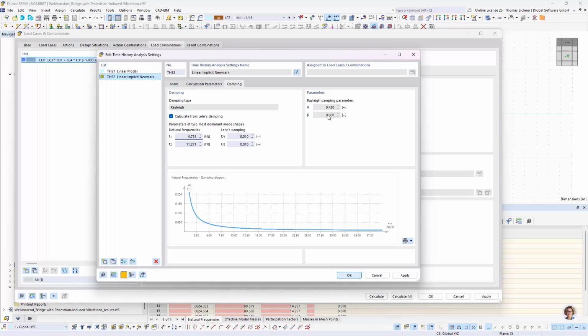The beta value also adds an additional asymptote beginning from the origin, with a slope that is defined right here. So as soon as you enter beta damping and you have an infinite frequency, this infinite frequency would have infinite damping, kind of. And that can lead to problems, at least in non-linear time history.